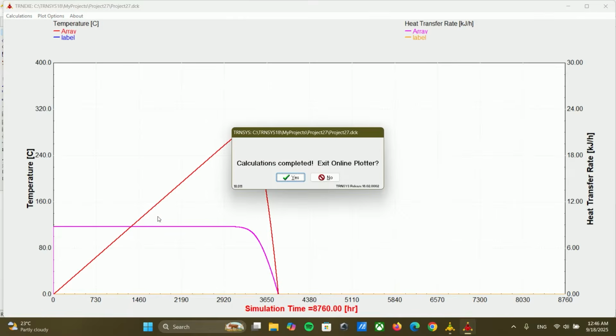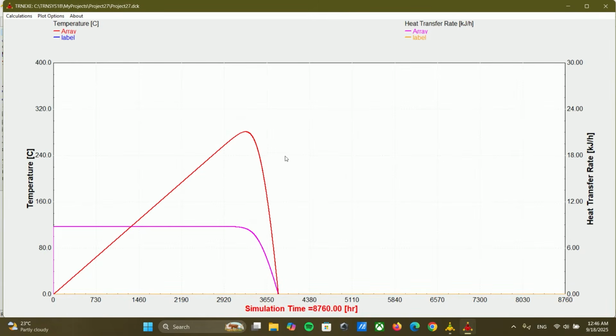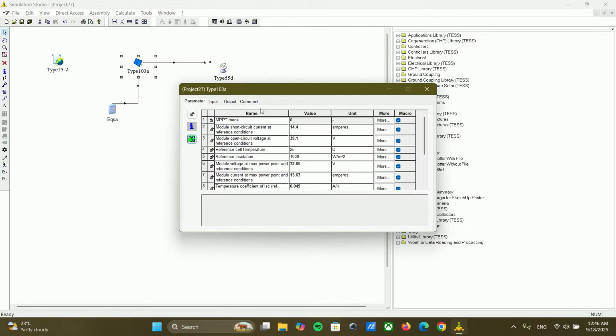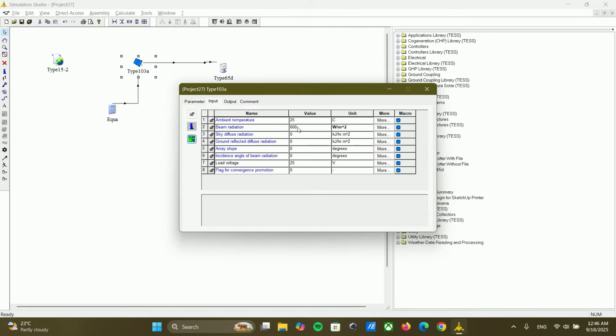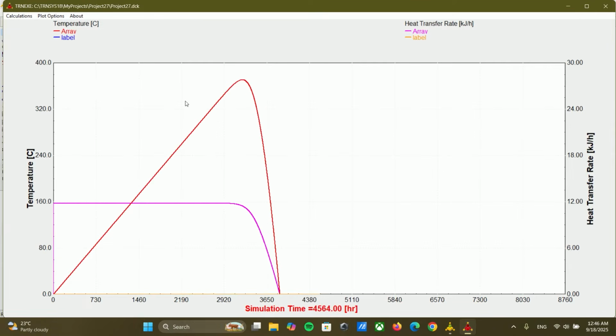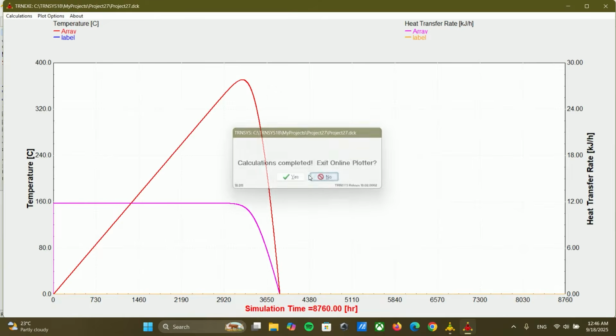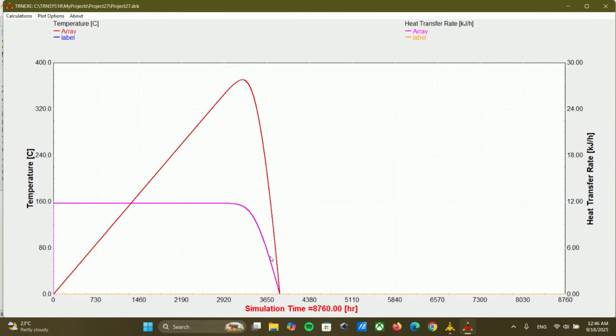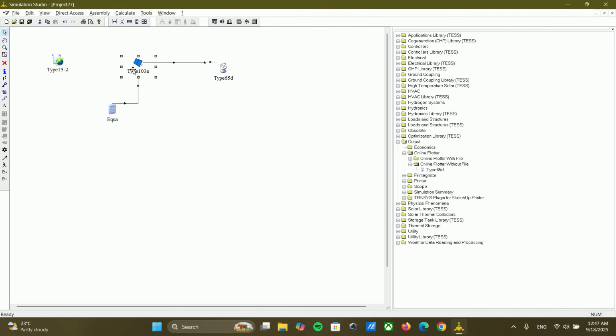It's changed a lot. Now, as I mentioned, this is also the difference that it makes. If I change this beam radiation, look how much it would change. So I would change it from 600 to 800. And you're seeing that if I run this, you would see this huge gap that is created here, because the first time it was about to this region and now it has increased. So the beam radiation defines pretty much that you're increasing the power on the surface of your